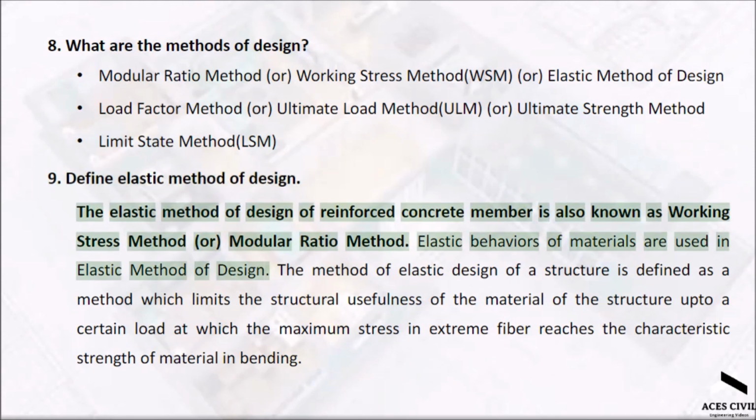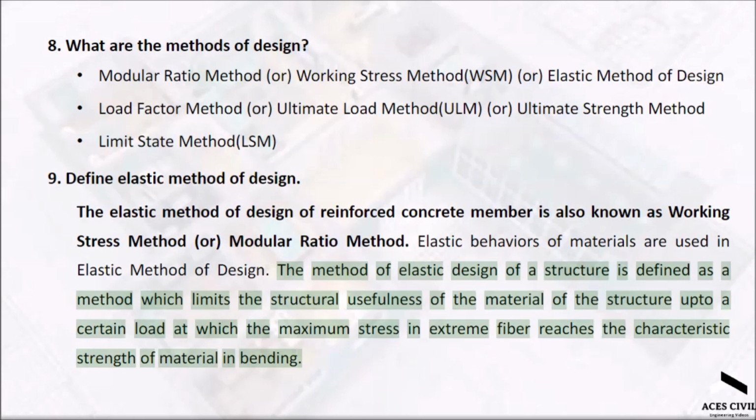The elastic method of design of reinforced concrete member is also known as working stress method, or modular ratio method. Elastic behaviors of materials are used in elastic method of design. The method of elastic design of a structure is defined as a method which limits the structural usefulness of the material of the structure up to a certain load at which the maximum stress in extreme fiber reaches the characteristic strength of material in bending.